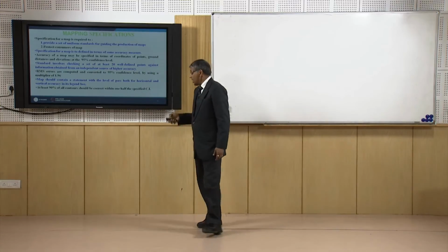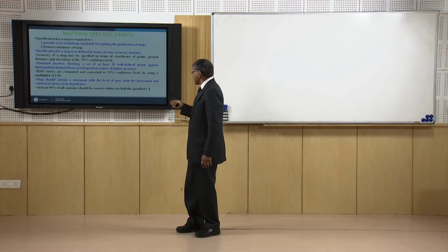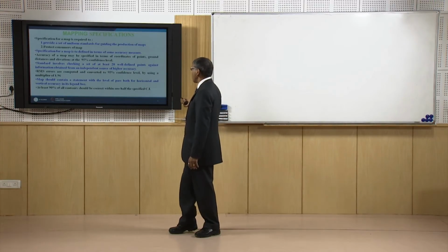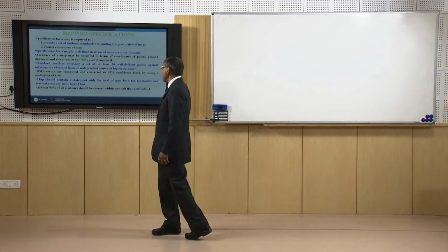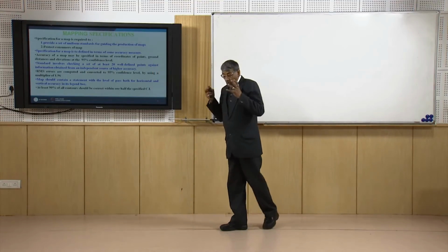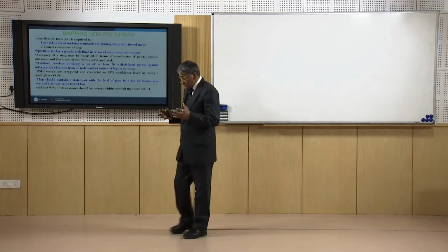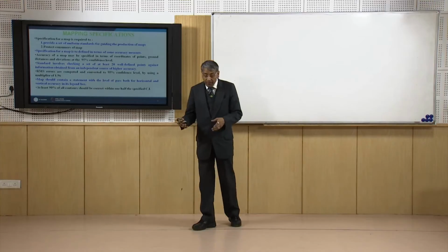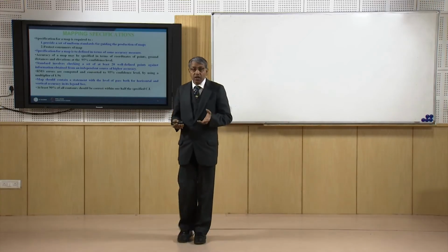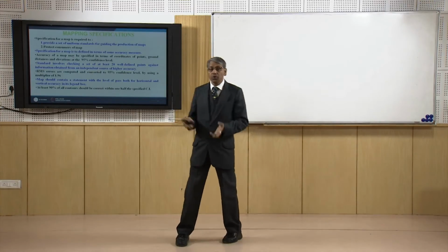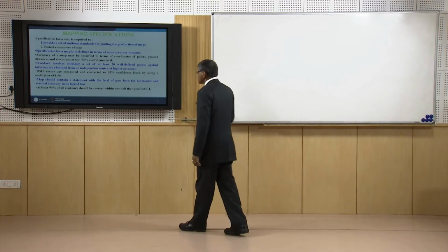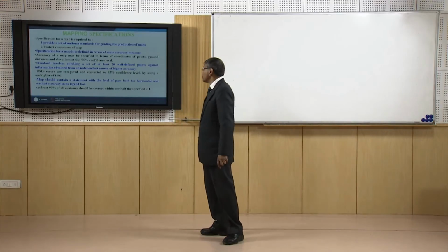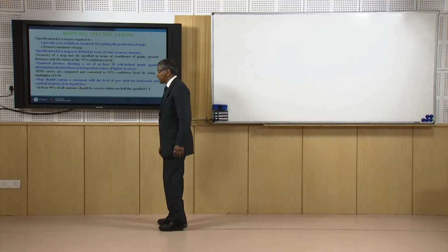We have to take a set of at least 20 well-defined points or ground distances or elevations, and for those points or lines or elevations we must have the same parameters measured using instruments having higher accuracy than the instruments or measurement methods we have adopted in finding out those parameters for this particular survey.